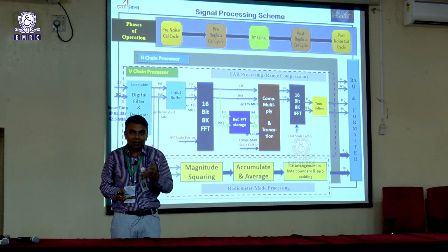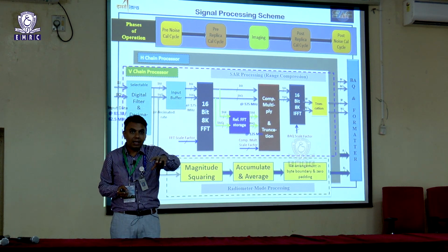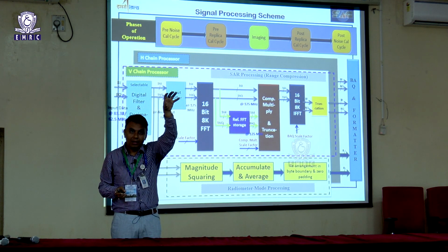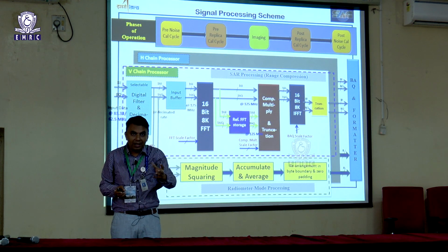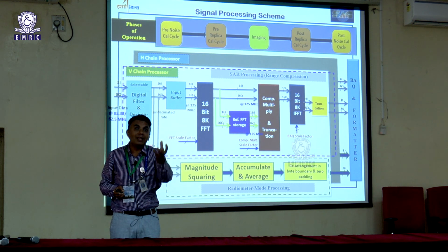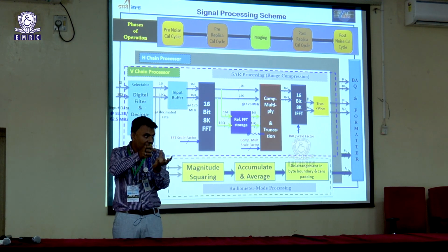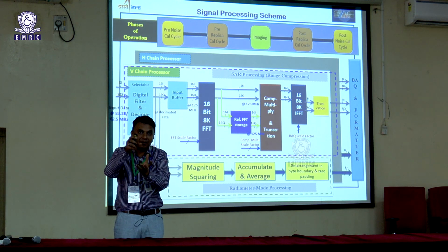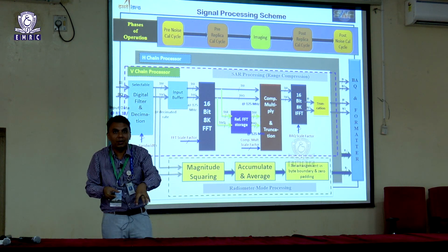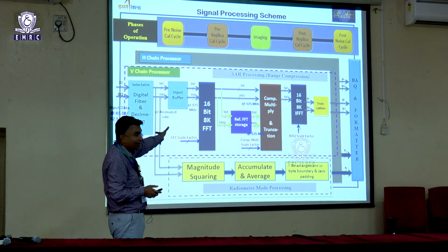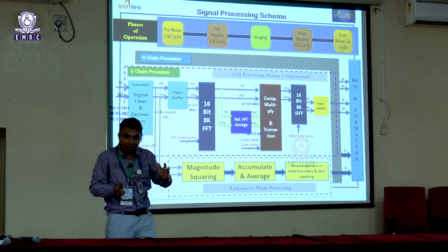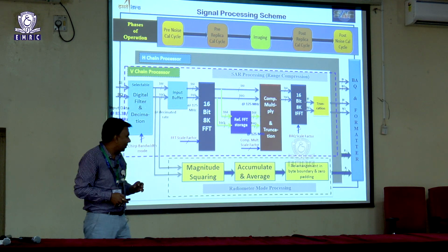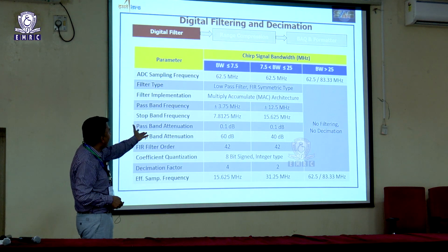So what we have developed, the technology I will tell you in layman's terms: we take the area where we want to land, put some small images, and store them in the onboard hardware itself. Once our spacecraft is nearby, we take a photograph instantly and try to match it with the onboard stored images. Once we get the matching area and are doubly sure that the image is perfectly matched, we find out that this is the landing spot. This whole algorithm sits in the DSP domain, where we stored all the onboard images, and once the real scenario comes, it computes against it. That is done using Virtex 4 devices.